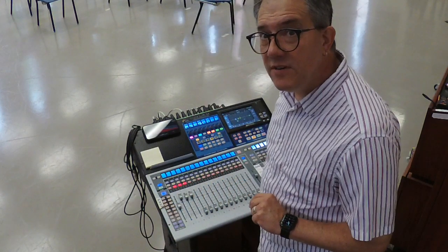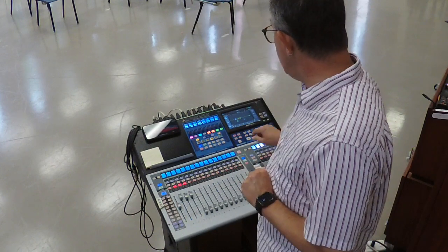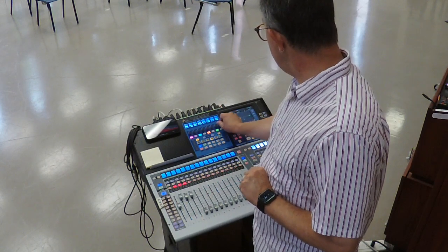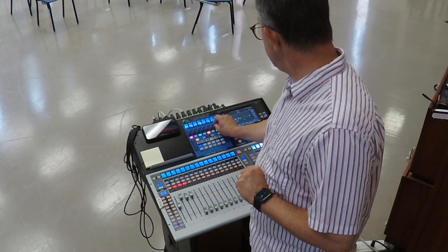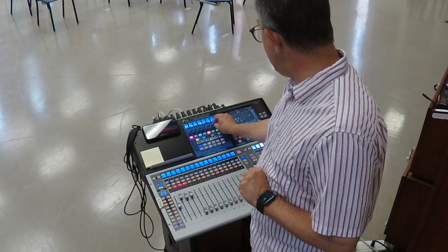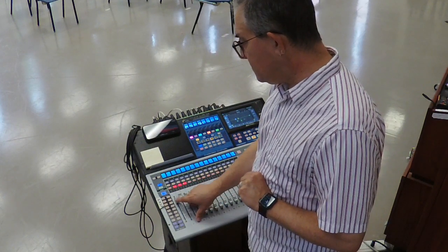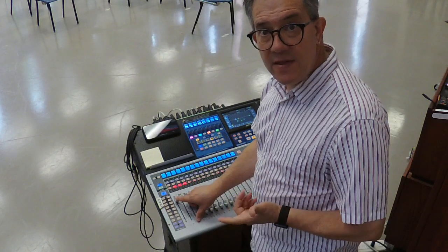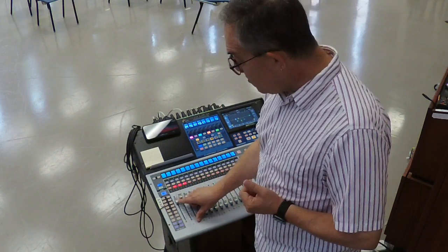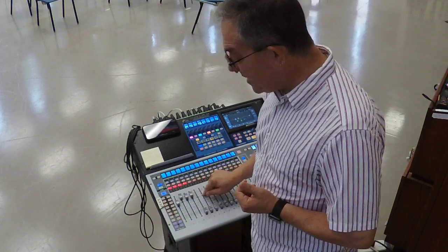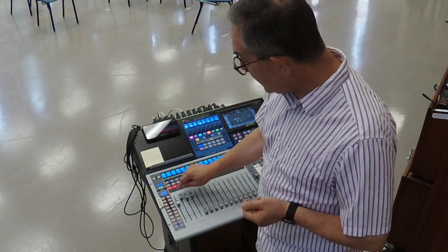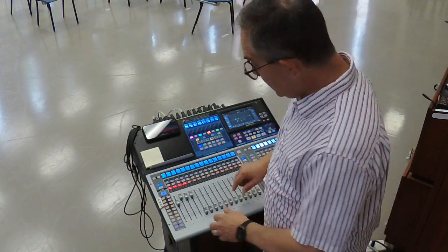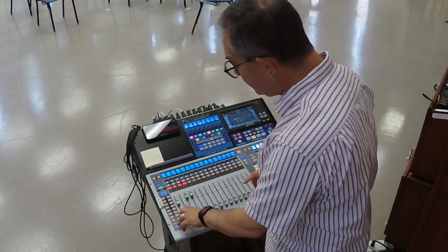So let's figure out where that higher frequency of feedback is. It thinks it's at 452 hertz. So let's go into one of my channels and find 452 hertz, and then let's actually turn the gain down on that. Now watch what happens. I'm turning it up the same amount I was before, and I don't have feedback on that channel. So now I have the ability to actually mute that and move on to my next channel, which is ringing at a different frequency.